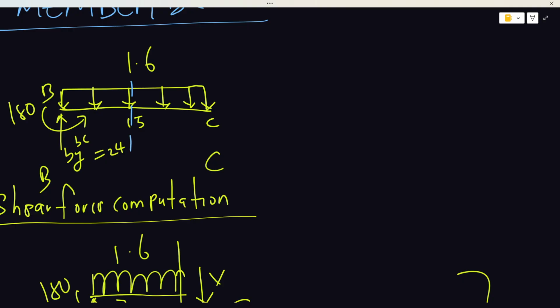Along B to C. Because the method of cutting basically works when you notice that this loading type is the same from a particular point to a particular point. But when you see that the loading now changes, you will go and cut it where the loading changes again and do the same, repeat the same process, get the new shear force equation. That shear force equation will be consistent from where the previous equation stopped working to where you cut it. Well, we'll explain more of this.